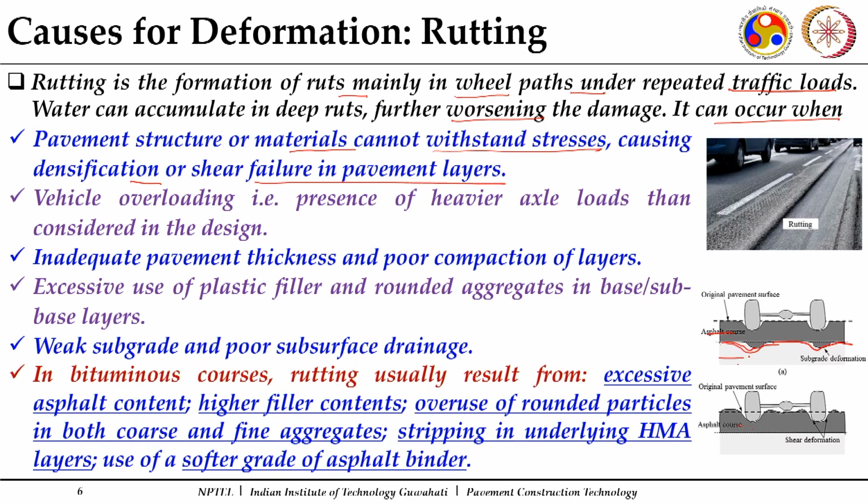Here this particular rut which has happened due to inadequate compaction at subgrade, in due course of time will get reflected on your top courses. So, the rutting which appears on the bituminous courses has a cause which lies at the subgrade level.